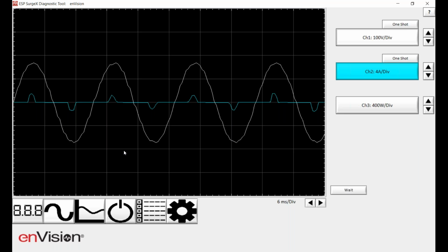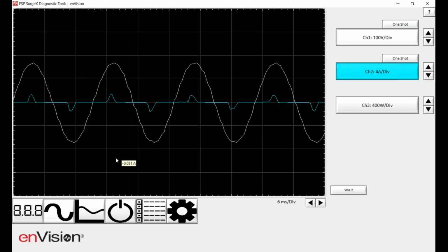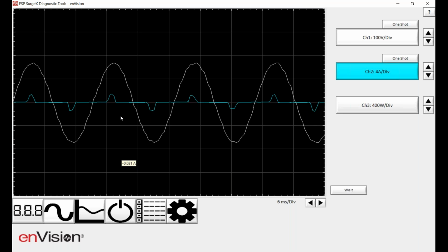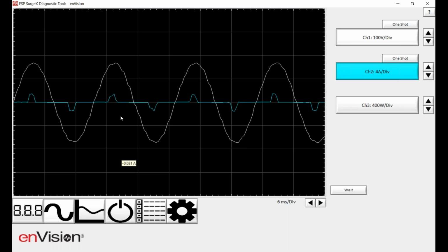But now let's say you feel like you've got a power supply issue, you're not delivering enough power from AC mains. So you call an electrician, he comes out, he sticks his meter in the wall, he says, oh, but I'm measuring 110 or 115. And that may be true, but what he's measuring is the RMS value, and we're not seeing the full picture, which is the impact of your supply being insufficient or your load being too great only at that one part of the voltage waveform. The RMS value may be 110 or 115, but where it's trying to pull power has actually been reduced by a much greater proportion because the peak has now been brought down, say 10, 20 volts or whatever. All right, no, that's a great point.